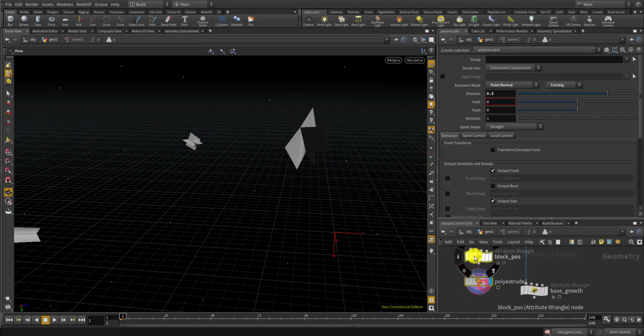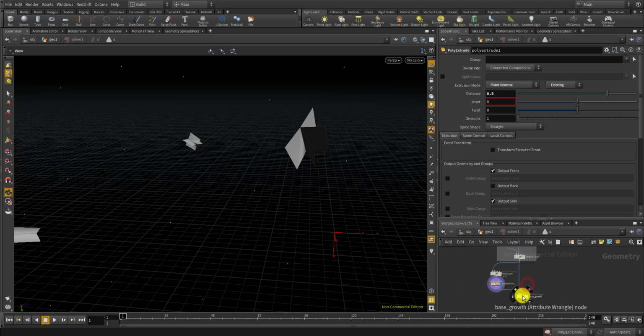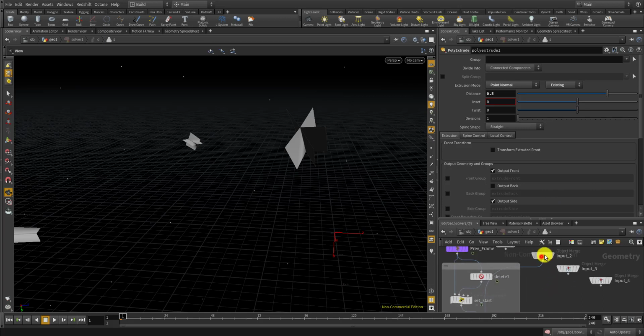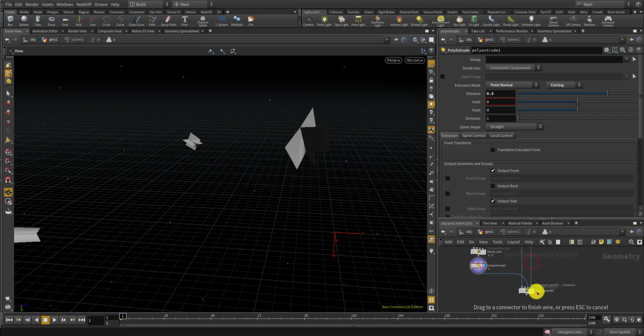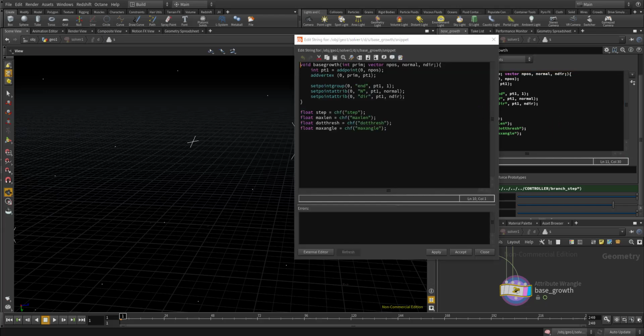So I'm gonna connect this block geometry to the third input here. Oops. And for the second input, I'm just gonna connect the reference point, which will be this one, which has the vector field, to the second point. Okay. Now it's time to calculate the collision, the intersection. I'm gonna use the intersect function here. First of all, let's make out attributes called allp and alluv, which I'm not really gonna use. I just need those variables in order to calculate the intersect.